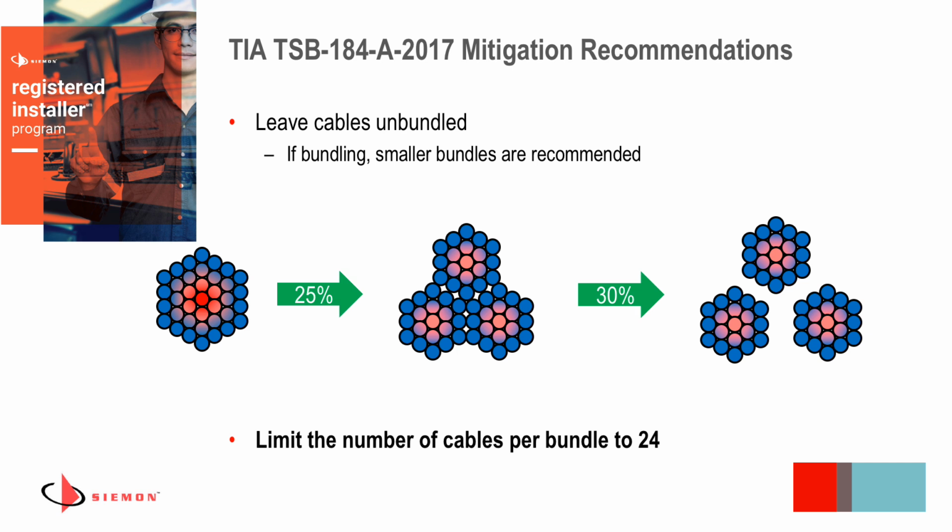A good rule of thumb is to limit the number of cables in your bundle to 24. You'll see on the next slide why that's important, but it's also a good number because 24 is the typical number of ports that you're going to see on a patch panel. So it's easy to manage along the pathway anywhere within the telecommunications room or otherwise. And 24 is a number that people work with comfortably in the telecommunications spaces for copper cabling systems.